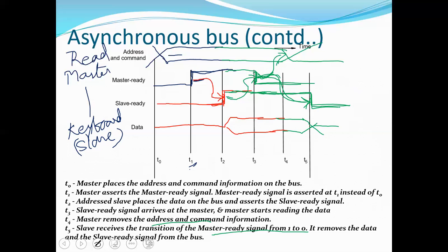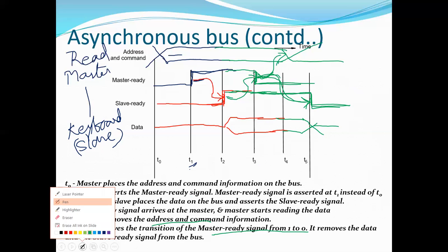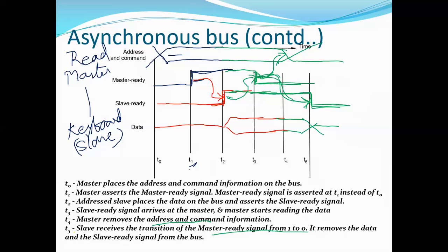Fine. So you can see there is a handshake between each and every task that is happening. It has received information from the previous step, like the master is set. This is the first event. Once the master is set, the slave recognizes this and is set. Once the slave is set, the master comes to know that the slave is set and the operation, a read operation here, is already in progress. So the master comes down, the third step.